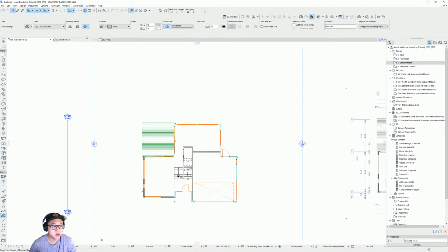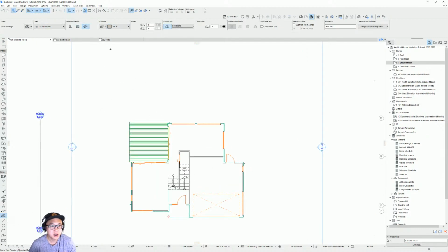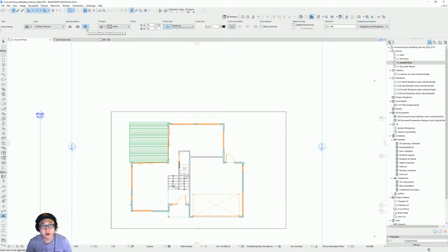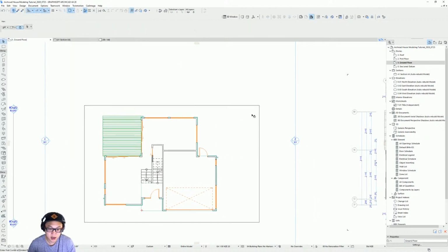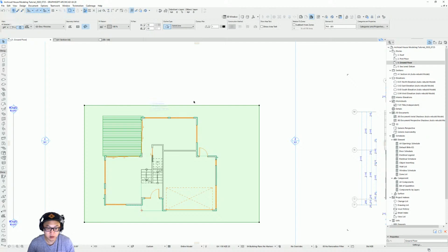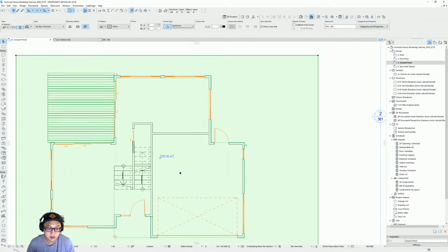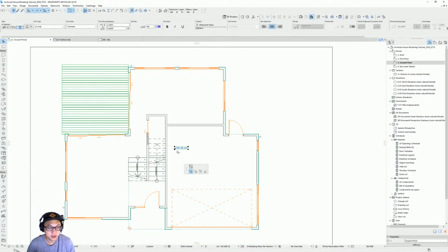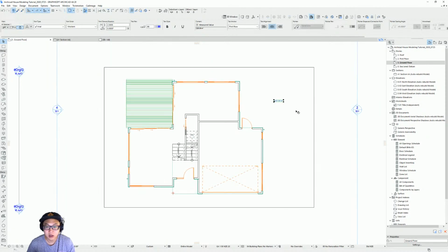First, I'm just going to use a fill tool, and I usually use this one instead of a line because I can create a proper rectangle and find out the area. That's possible because I use the rotated rectangular method. And what's good about using fills to look at areas is that you can just show area text and it will give you, well, not roughly, the exact area of it.